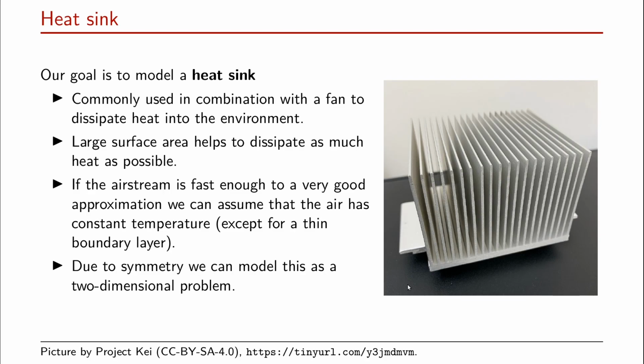So that means that basically a fan blows air through the ribs of that heatsink, and this means that the heat in the heatsink is getting exchanged with the environment, and the moving air carries away that heat. And the whole idea, of course, is that whatever device is generating this heat is then kept at an appropriate temperature. Now, really the fundamental physical part here is the large surface area. The larger the surface area, the more energy we can exchange.